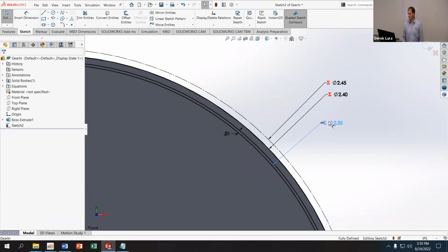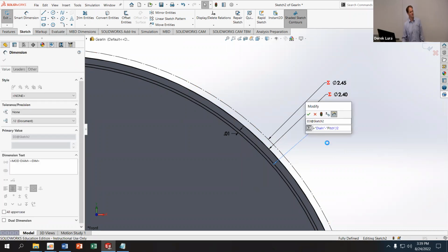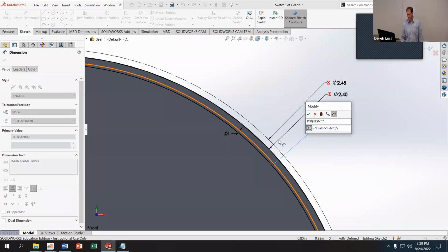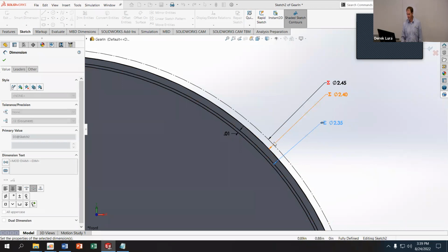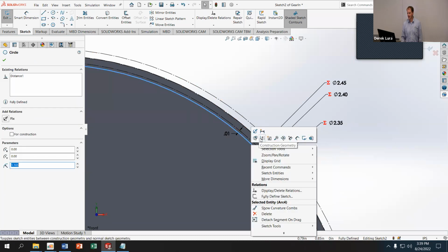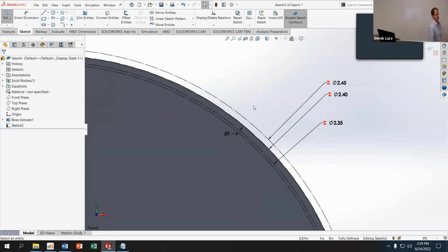The second to last one, this one is the die-in minus 1/2 of pitch. So it's the effective diameter plus 1/2 of pitch, the effective diameter minus 1/2 of pitch, and then a 1/100th of an inch clearance. So why 1/2 of pitch? For this one, it doesn't really matter since we're not going to be using these lines as solid lines, but by making them construction, it's easier for me to visually differentiate the outline that I'm going to use for the cutout from the guides that I have here as a reference.